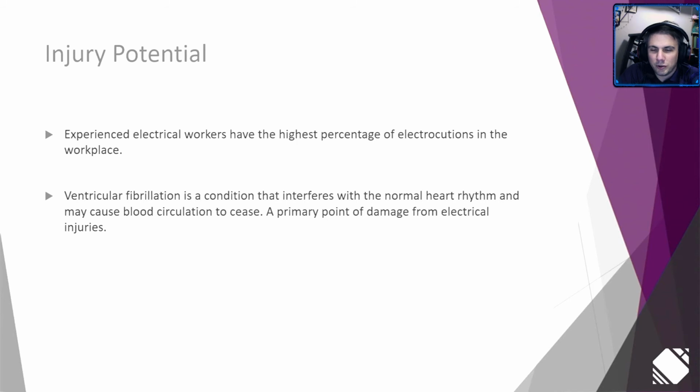It usually tells you that you shut off the wrong breaker and you should have used a tool to check and make sure that that power was off before working, but at least you're not dead. Now, if you reached in with two hands, you've got two hands across the system, and electricians will call it their two-hand rule. Work with one hand, not two, and the reason being, if you go with two hands, now that path between the fault goes up your hand, across your chest, and out the other arm.